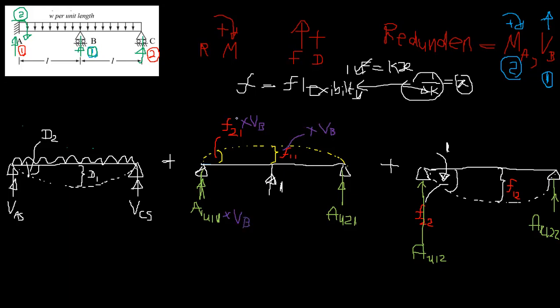You remove the VB and apply a unit force and get the output, and you multiply the output by that value. Because people have derived this appendix for displacement for a unit force, because they can't derive it for every force. So it's easy if we use unit force, and we can multiply it by the value V1, right?